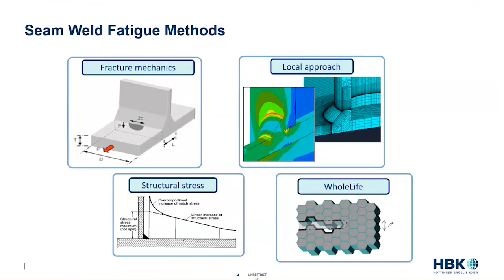There's another approach to the left called local stress. And here we actually model the weld in reasonable detail in our FE model, either in the global model or maybe as a breakout model that receives things such as displacements or loads from the global model. It has certain advantages in the fact that it starts to characterize more of the weld geometry. And so it can look at, a bit, at things like weld quality. But on the downside, if this approach is put directly into the global model, the mesh density is such that you really can't analyze anything real. You know, it's just the refinement that has to go in and capture the weld behavior. Basically, it's going to just make it unusable.